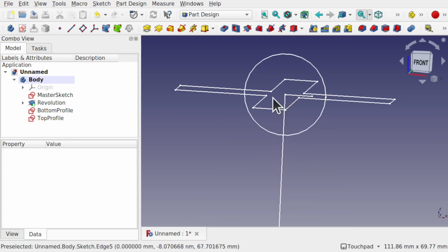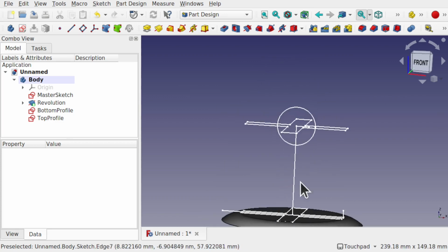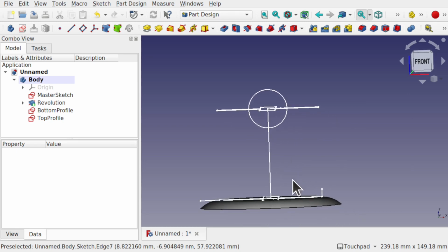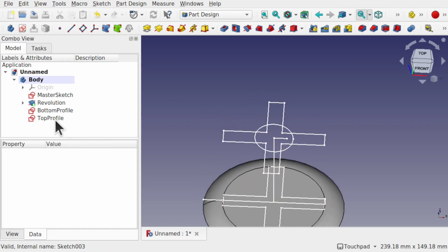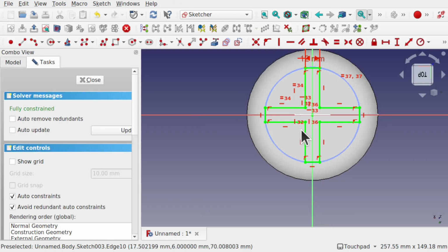And that's placed that there. So directly upon there. Now, if we've changed this and we actually started this revolve on this point, then we would have to minus this height off. So this height here, but we didn't, so we're okay. At the moment, this profile is way too big. So let's come into that top profile and adjust that.